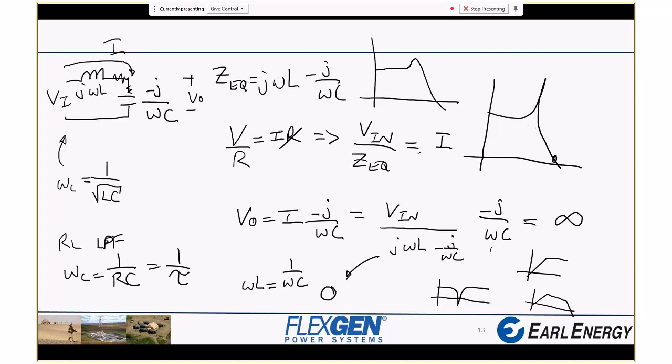What you can do with clever DSP control or even analog control is make the circuit think that you can put in a virtual resistance by feeding the current of the system back, and you can essentially modulate the voltage to make it look like there is a resistance.